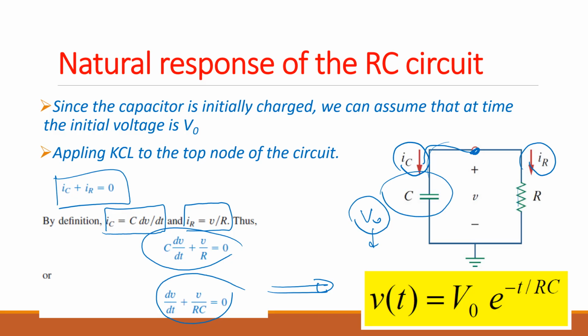So when the capacitor is discharging, the voltage across it is changing from V naught to 0. V naught is the initial voltage, which is when it is charged, and we can find the voltage at any time t using this equation. Here e is the e in your calculator, t is the time, R is your resistance value, and C is your capacitance value.